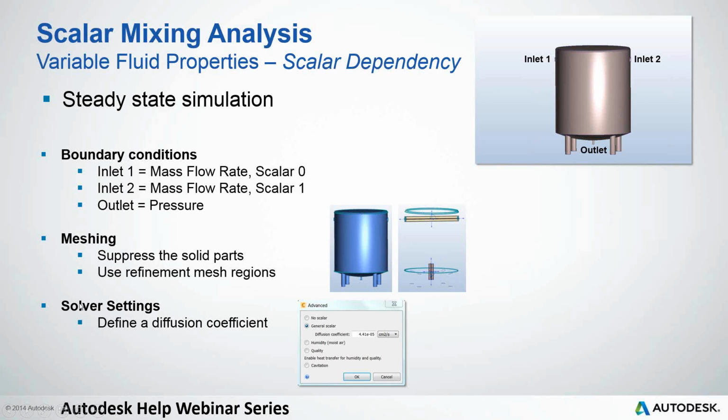For the solver settings, next to saying that this is a steady state analysis, as already mentioned by Marwan, you have to set the general scalar of water and methane in this case, the two fluids that you are simulating.